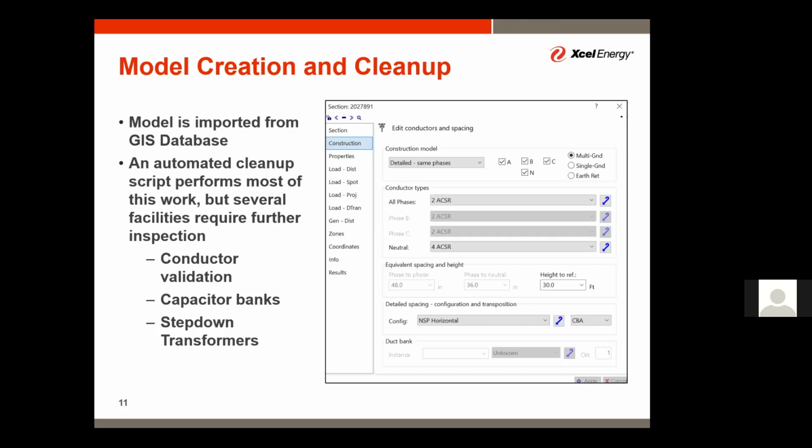And one of the main issues is new generation being added or excess generation, like we're talking about in this case. So if we see hosting capacity diminished by a certain amount on this feeder, we go in and look at those specific details of those feeders and the amount of DER that was added there to see if that reflects what actually happened and if those results are really what they should be in the end.